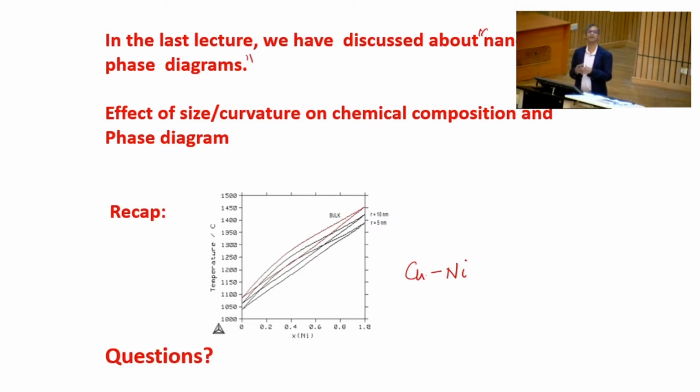Well, if you mix copper and nickel in any proportion, starting from 0.01% of nickel into copper to 99.9% of nickel into copper, or vice versa, the phase formation is the same. That is, you will have a single phase forming, the FCC solution between these two elements. So, that means it forms a continuous series of solutions, and it does not matter what the composition of the alloy is.